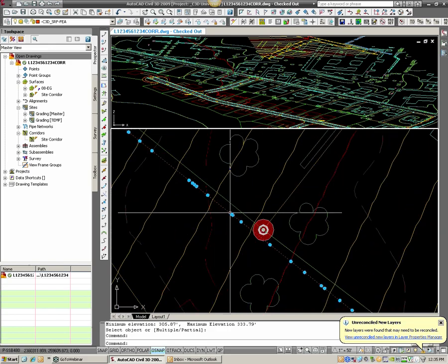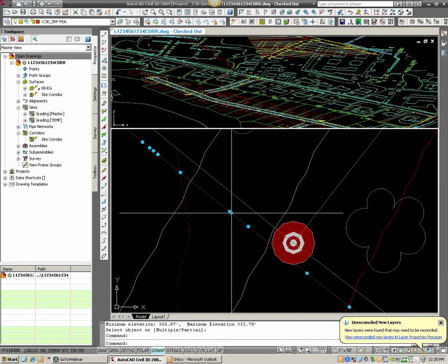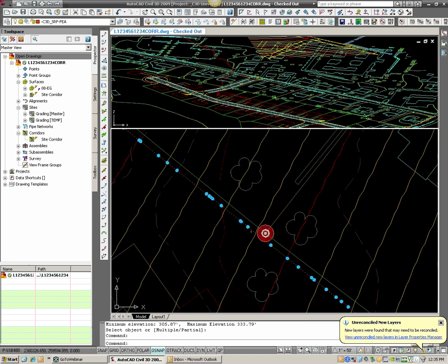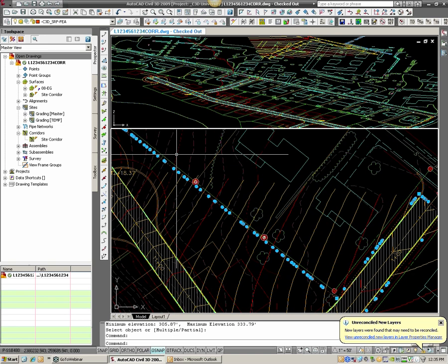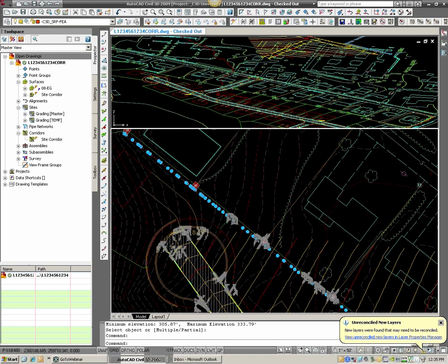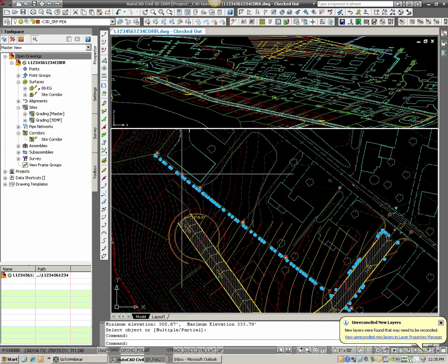Also, you can see they're sort of random. These two are pretty close together. These are pretty far apart. It really depends on what your existing surface is. This is probably a closer match to perfect existing grade, but like I said, it doesn't pull as nice as if you add elevation points and then just drape those elevation points right onto the existing grade.